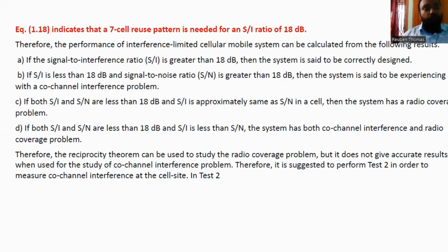Therefore, the reciprocity theorem can be used to study the radio coverage problem, but it does not give accurate results when used for the study of the co-channel interference problem. Therefore, it is suggested to perform test 2 in order to measure co-channel interference at the cell site. So this is about handoff and all the technologies which have been covered.